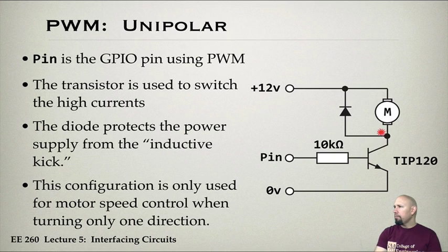So that's how this works. This is a 12-volt DC motor, and the transistor handles a higher current than the Arduino can handle. The current coming out of the pin goes through a 10K resistor and then to ground, so there's not much resistance that this pin is going to see from this circuit. It's going to see at least 10K of resistance, and that's not a lot.